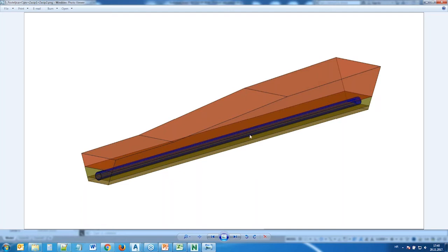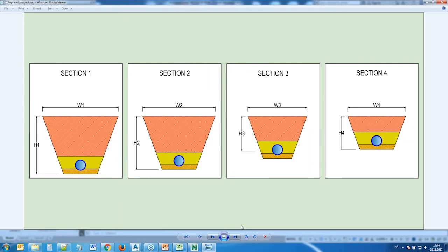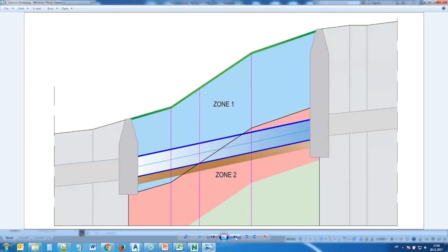The ground moves, for example, and we take these points where there is a change in the distance between the ground and the pipe, and we make sections in these points. So in this case, the sections would look something like this, and we calculate each of those sections, and from those sections we extend them, and we make the trench calculation, the trench volume.